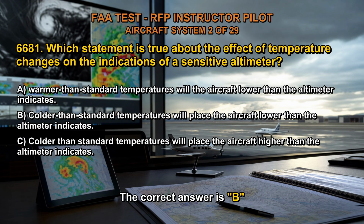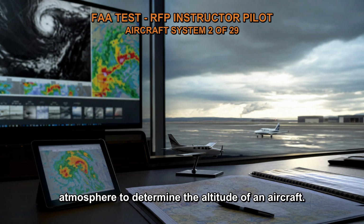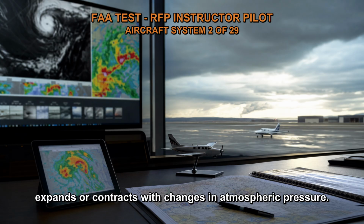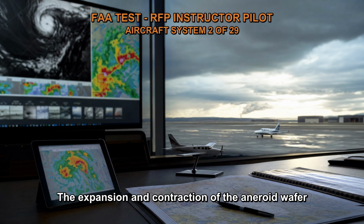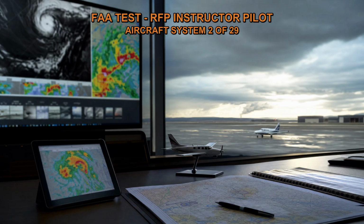The correct answer is B. A sensitive altimeter measures the pressure of the atmosphere to determine the altitude of an aircraft. The altimeter uses a sealed aneroid wafer that expands or contracts with changes in atmospheric pressure. The expansion and contraction of the aneroid wafer result in corresponding changes in the altimeter's indications.